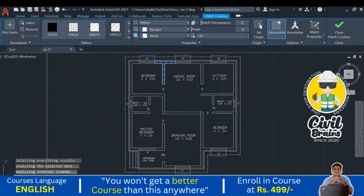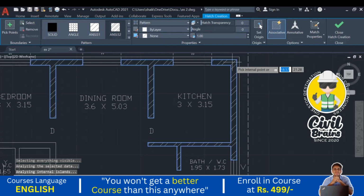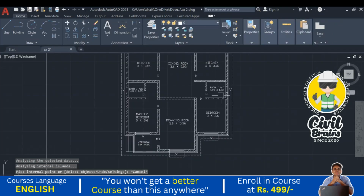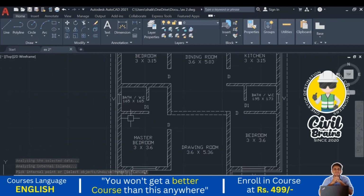Click on the points. I just show you, I zoom it. Here you can see this one point. I just zoom, I just click here, just click here, automatically it will take. If any gap will be there, if the line is not joined, then it will not take. Okay, so if there is any joint, any gap, it will not take. See here, it will take like this. So hatch will go out. Okay, clear? Okay, so we have hatched all the walls.